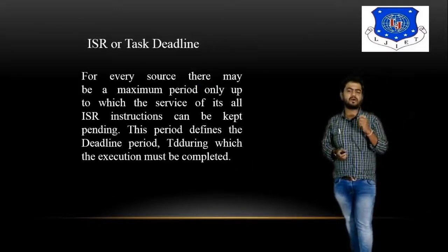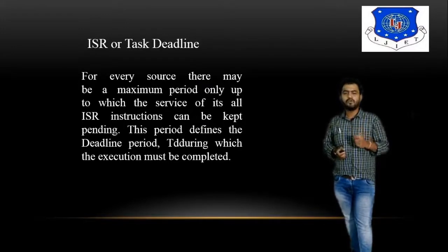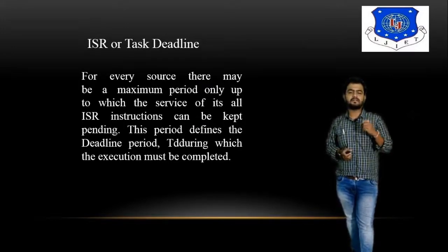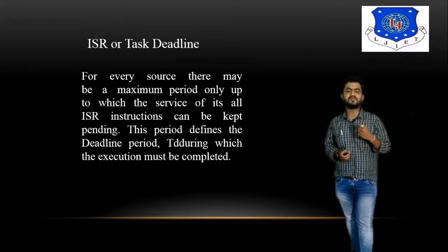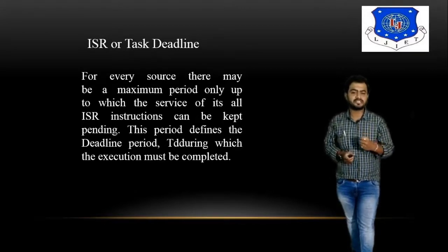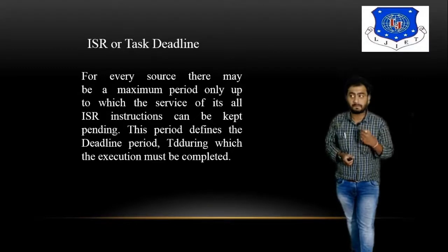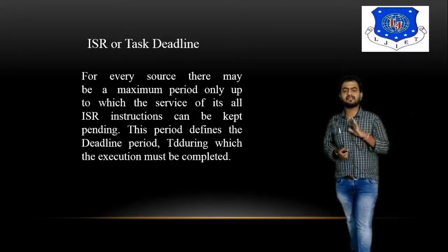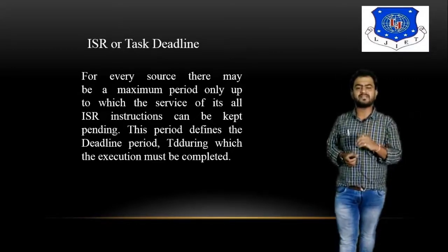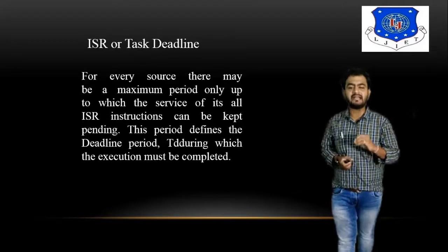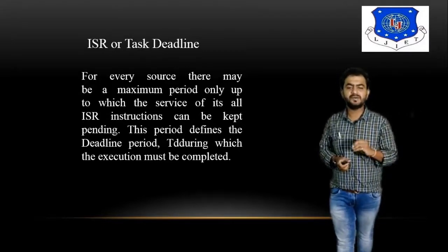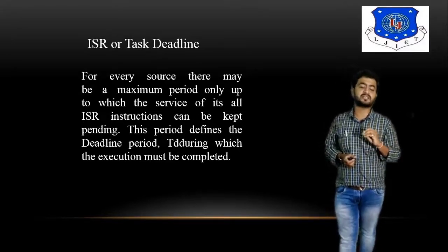ISR: what is ISR or task deadline? For every source there may be a maximum period only up to which the service of all its ISR instructions can be kept pending. We can say that all the data will be kept pending. So this period defines a deadline period TD during which the execution must be completed.